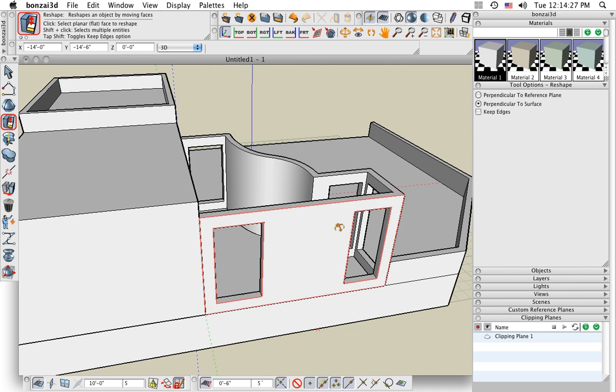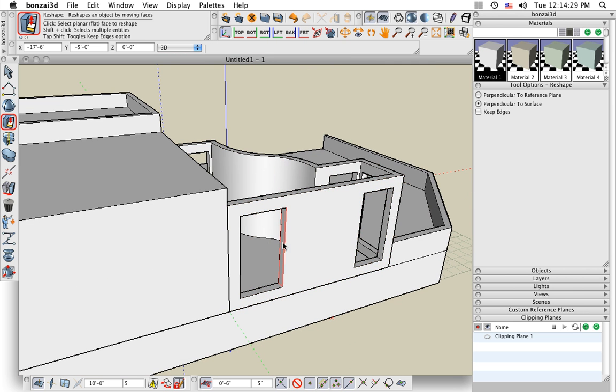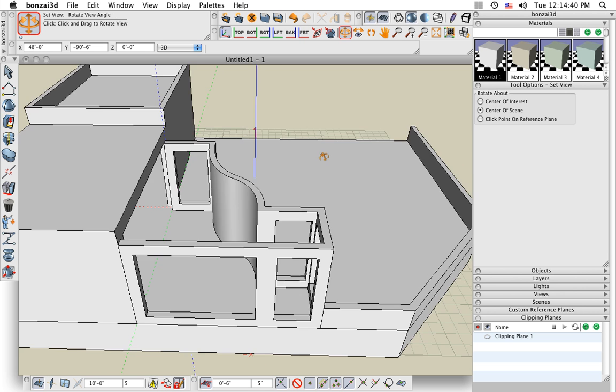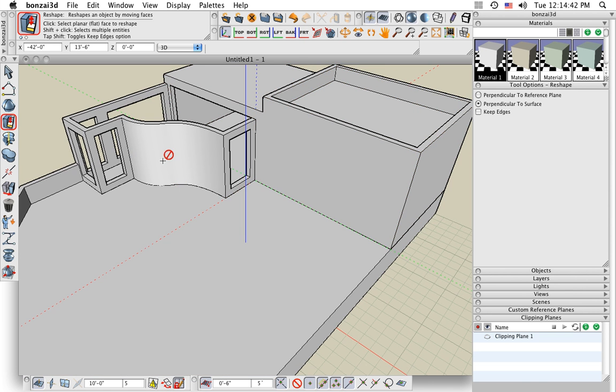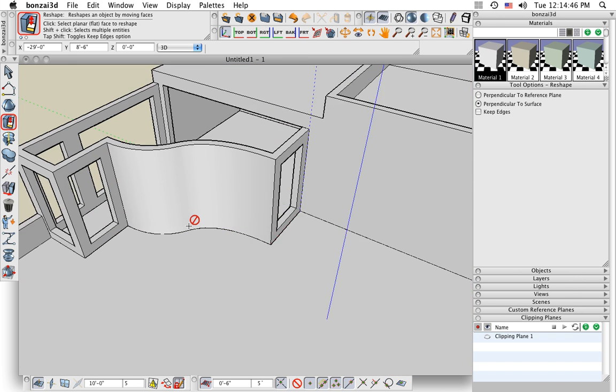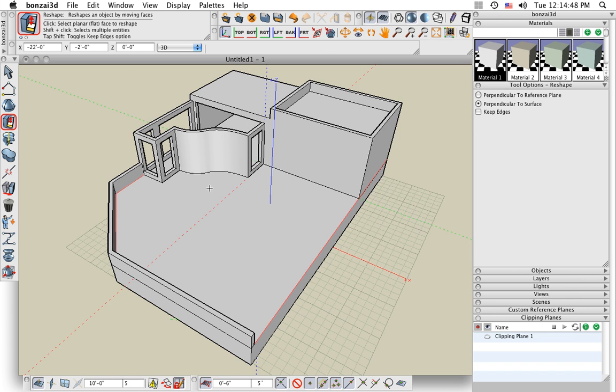Of course, you can also use the same tool to then adjust the size of the opening, and again, using snapping, it makes it easy, for example, to line up one size of the opening with another feature of the model here, just snapped to the corner on the other side. Okay, how about an opening in the curved wall? We can do the same thing, just a few different steps.